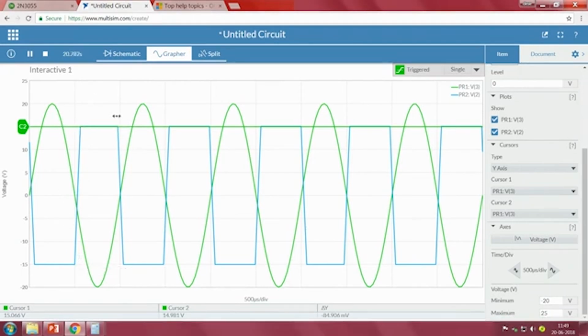So, that is what we require. When do we have to switch on? When the temperature is lower than the lower threshold value, then it has to switch on. So, observe the temperature. If I say the green color one is the temperature, it is increasing, and at this point it is off. So, no power. Since there is no power, it will start cooling because of the convection, or if you have any forced convection, that is also fine. So, it starts cooling.